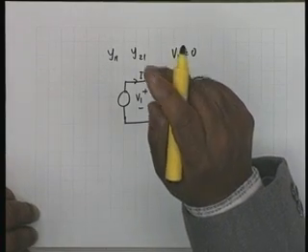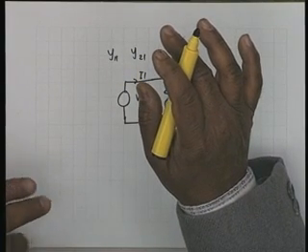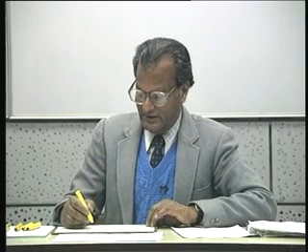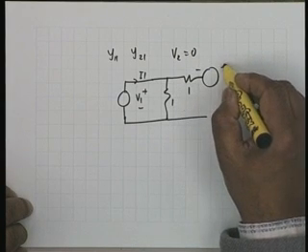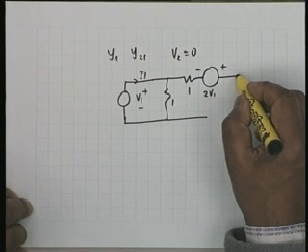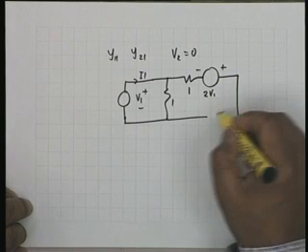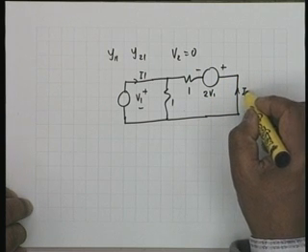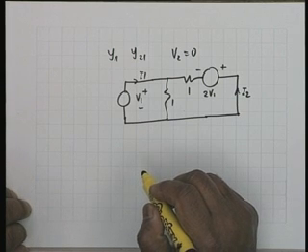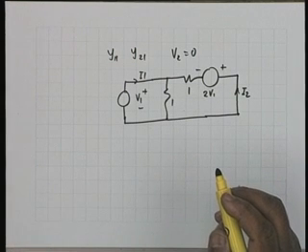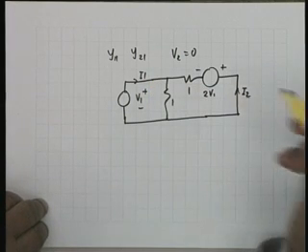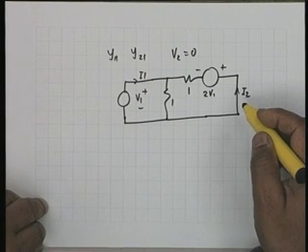That current generator vanishes because V2 is made equal to 0. Okay, the current generator vanishes and therefore I have minus plus 2 V1 and a short circuit, the current through which is I2. All right, this becomes the circuit, and what we have to find out is I1 and I2.